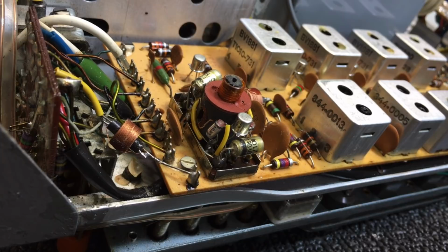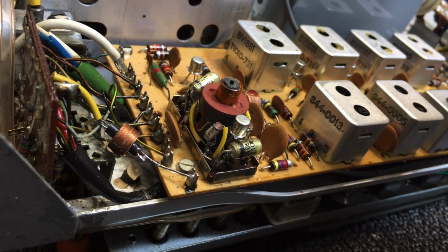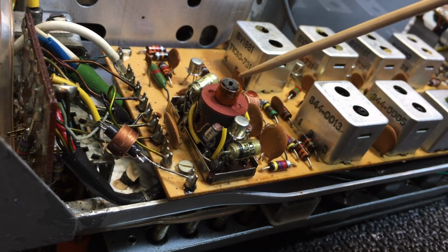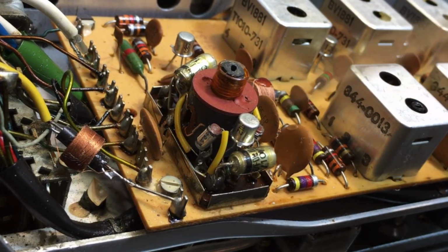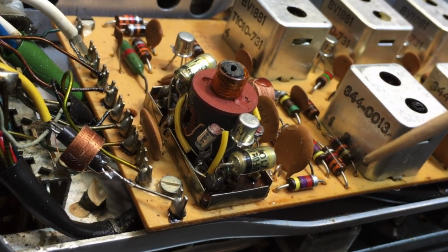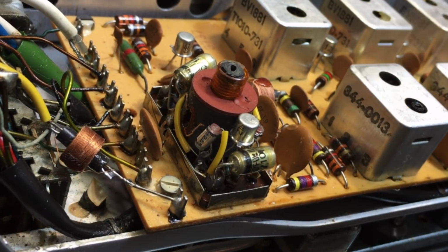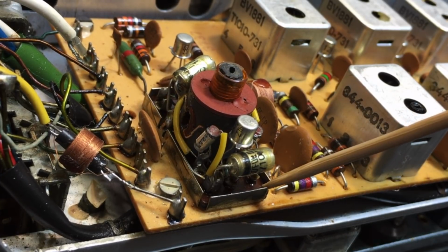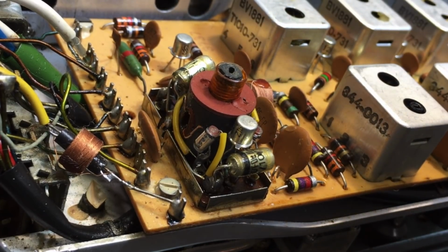And this is it over here. You've got all the components that are on that schematic crammed into this space over here with the tuning lug sticking out the top. There's that transistor. There are a few capacitors, a few resistors. What you need to do is to make sure that you've got all the supplies on here. And I've done that. I've checked that ground is there. And I've also checked that the B plus is coming in, and the B plus comes in when you switch on the BFO.